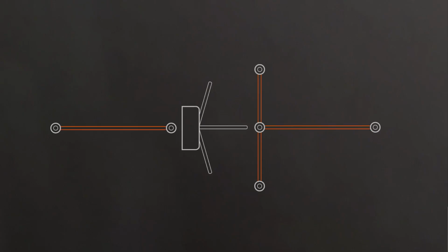To avoid such errors, it is necessary to properly install the barriers used in conjunction with them. Specifically, a passage former can be a special fence section, another turnstile, a wall, or a column. It should be installed perpendicular to the top bar of the turnstile at a distance of 5 or 6 centimeters from its edge. The length of the passage former should be between 80 centimeters and 1 meter. When forming the passage zone, it is necessary to consider fire safety requirements for the proper organization of evacuation exits from the premises.